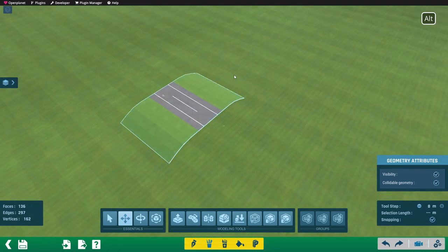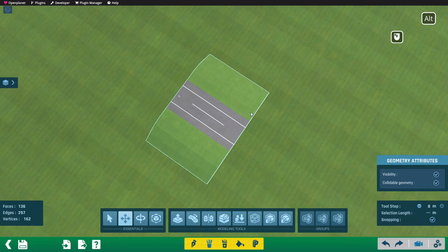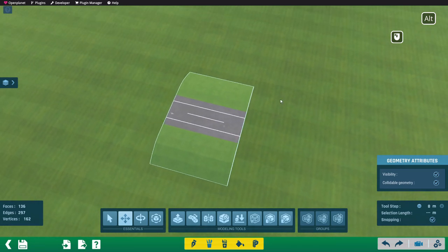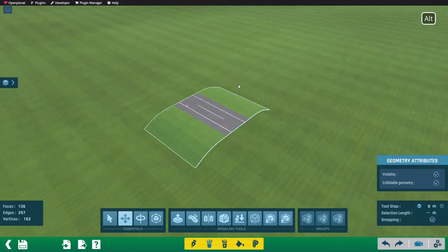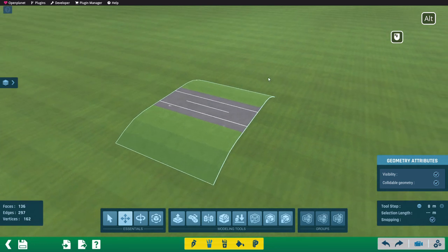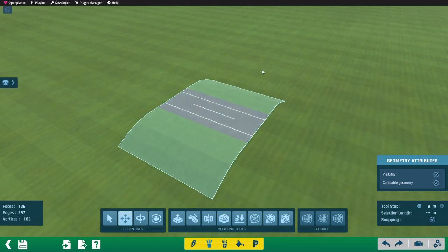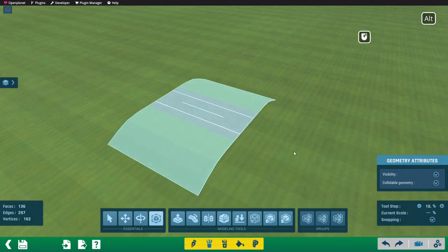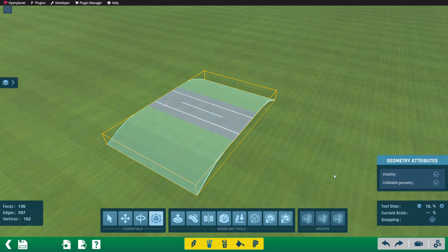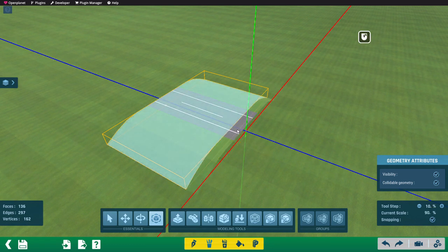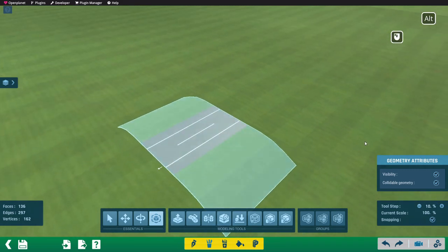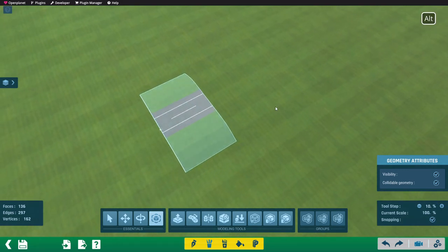So let's create a 15-degree turn. The problem is that the deformation tool creates bad results when we just make a 15-degree turn. But what we can do is to make a 90-degree turn and then remove everything after the first 15 degrees. But here comes the problem into play, that the deformation tool somewhat contracts the item, so we end up with something different than 15 degrees. But there is a solution for this which I will show. First, we decide what radius we want to have. In this case, 100 meters.